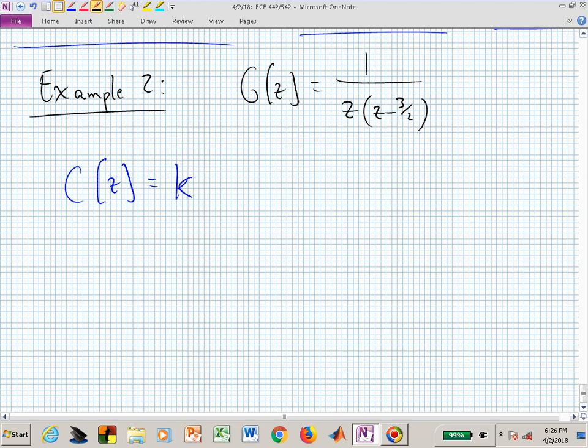One pole is outside the unit circle, and all it takes is how many poles for things to go bad? Just takes one. So that one pole at 3 halves, or 1 1/2, is causing problems. So we have an unstable open loop system. Can we actually stabilize it with a proportional gain, k? We learned in the previous example that we had a range for stability of k. Can we find such a range for this example?